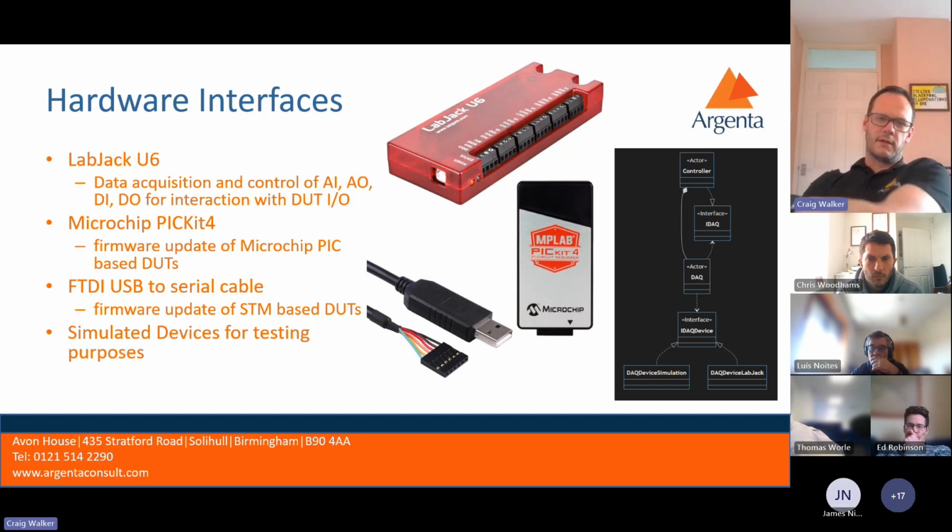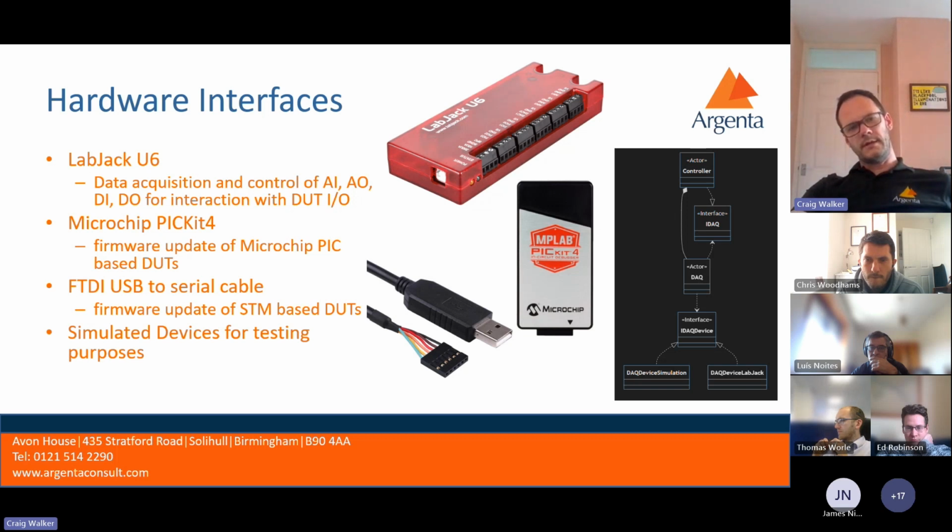As I was talking about, in terms of the actual architecture of these modules, we basically have the controller talking down to the DAC module, the DAC module talking back via an interface to the controller, and then another interface underneath that, which means we can inject hardware at runtime depending on which type of hardware we want to work with. In this case, one being a simulation and one being the LabJack itself.